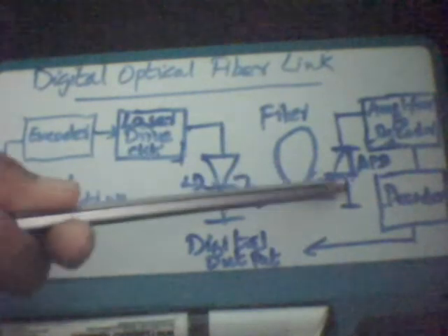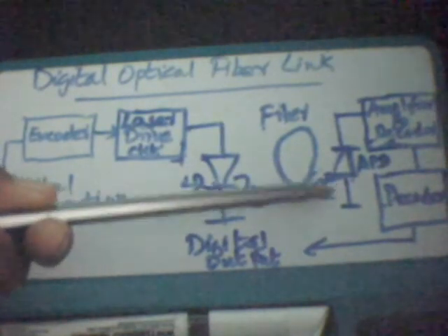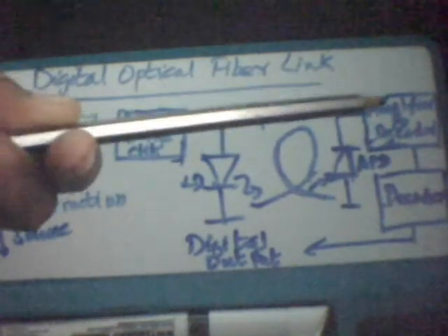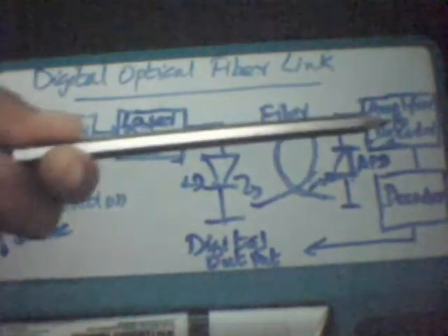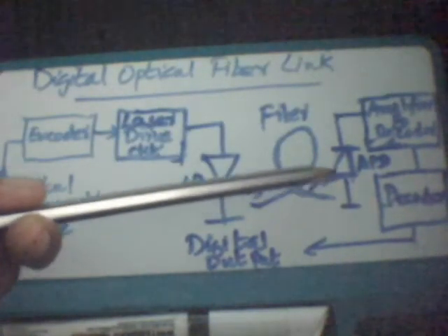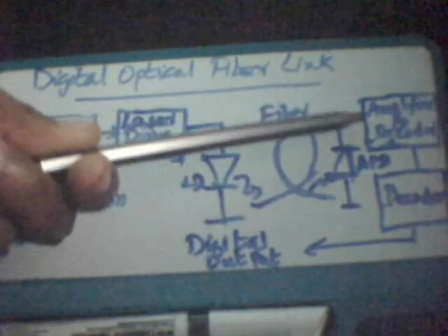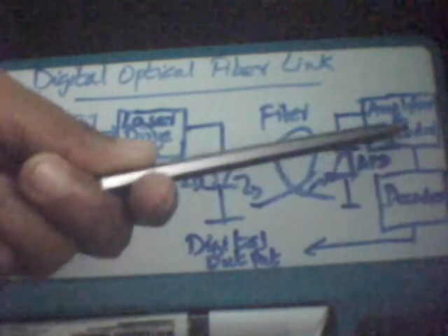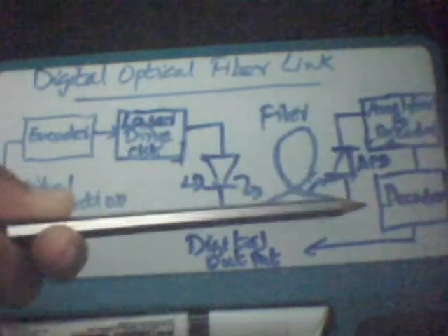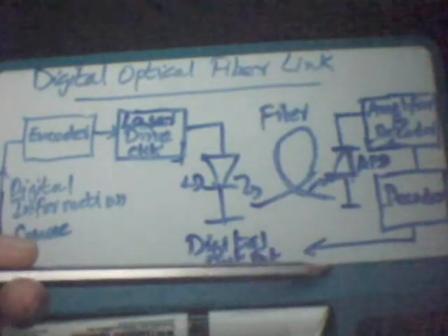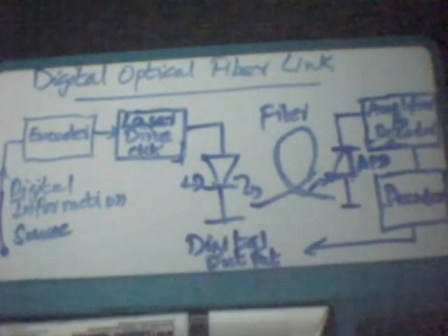The avalanche photodiode detector is followed by a front-end amplifier and equalizer or filter to provide gain as well as linear signal processing and noise bandwidth reduction. The avalanche photodiode converts the optical signal back to the electrical domain. Finally, you can see that after processing, the signal is decoded and the original digital information is retrieved.